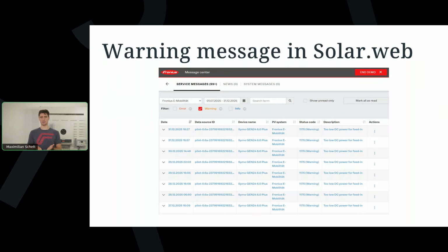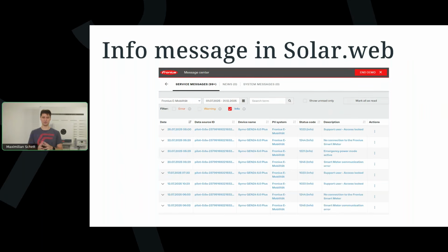This is information our customers get every day, or almost every day, when the sun is rising and there is sunshine, but not enough that the inverter can start producing. Then you will get this information. So it's not an error and nothing really to respond to. And even more, this holds true for info messages. You see it listed up here, for example, emergency power mode active. It's just information, there's nothing wrong.